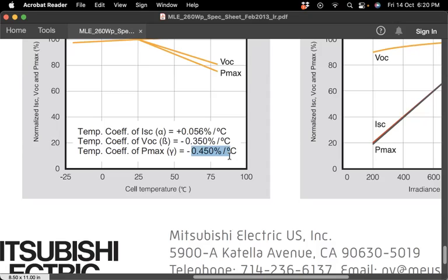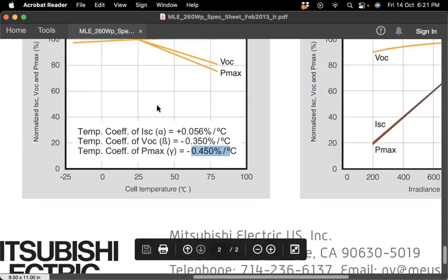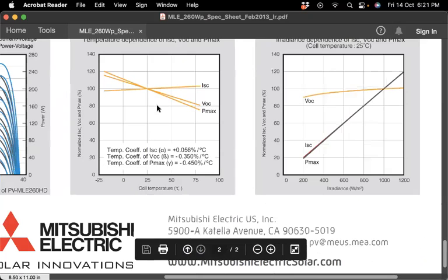So if you have a 4.5% reduction, which is nearly 5%, this destroys the overall sizing process. Accordingly, you have to take care of this effect and oversize your system to avoid any degradation or reduction related to temperature. That's why considering temperature is a very critical parameter in solar cells.